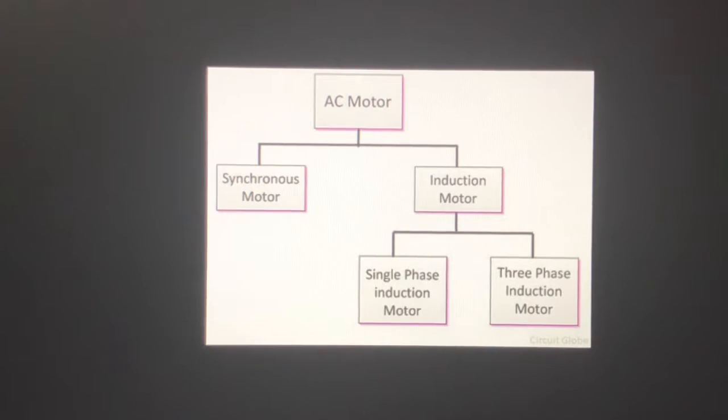This kind of motor is used even in high precision positioning devices like modern robots. They can also act as stepper motors. Induction motors are the most widely used and are very important for many industries due to their load bearing capacity and flexibility. Unlike a synchronous motor, this motor slips when compared to the stator current field. They are generally used for various types of pumps, compressors, and act as prime movers for many machineries.